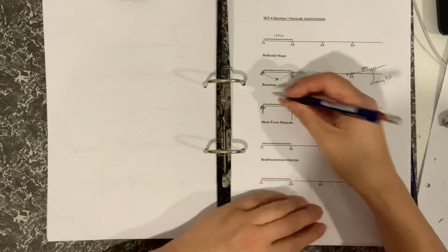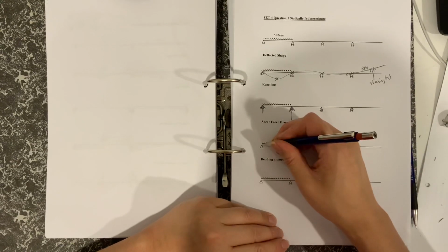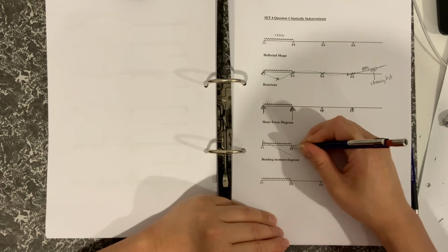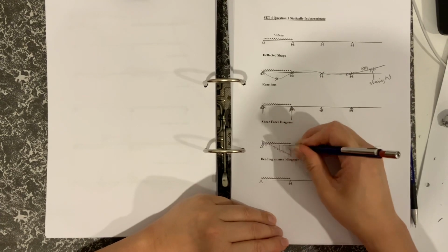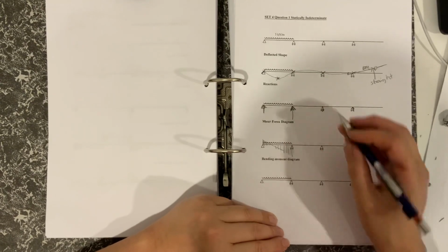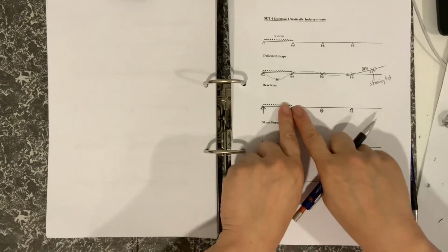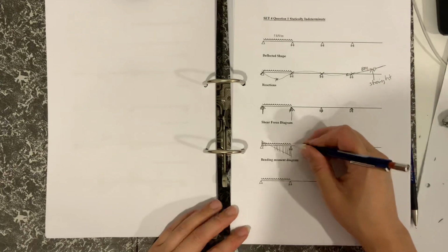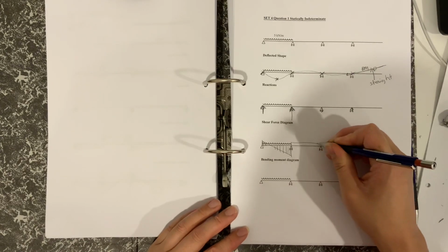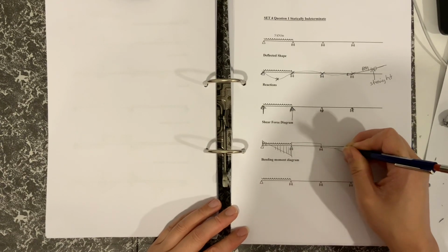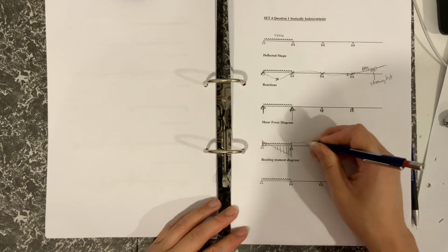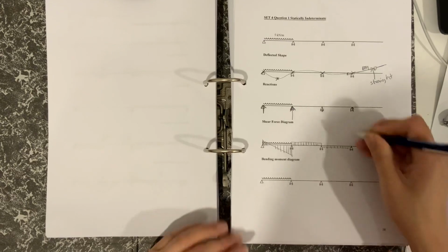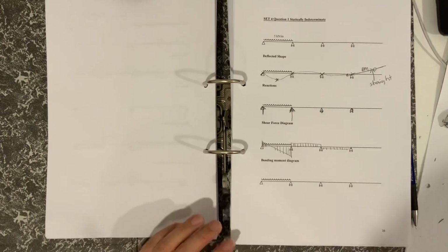So the shear force diagram, you would expect that to be up, and then you would expect that to be down. This one being bigger than this one, because there's more beam stiffness here. This is just at the end. Then that would have gone up a bit, that would have gone down, and then gradually go down to 0. Okay, which we can see there by the relative dimensions of the arrows.